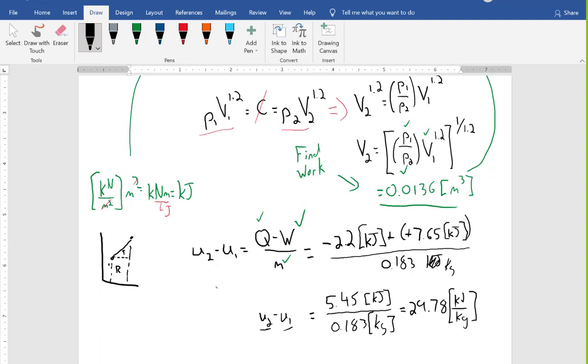You could also sometimes get a constant volume process. Constant volume processes are awesome. This one's a little tricky though, because if you try to do the math, you might get tripped up as you go from state 1 to state 2. But again, if you draw this out as a PV diagram, you'll notice that the work is the area under the curve, right? So what's the area under this vertical line? It's 0. So if the volume doesn't change, the work is 0 in a closed system.